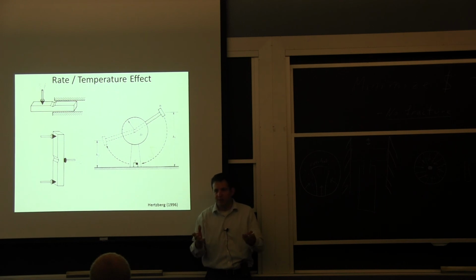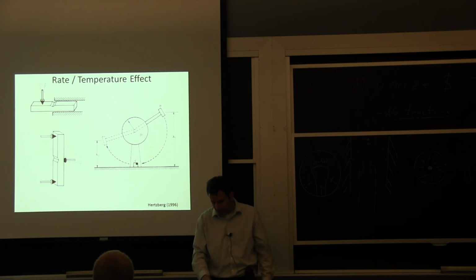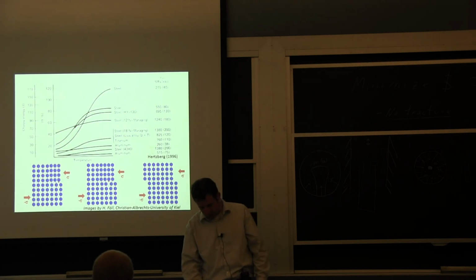But it's giving you a combined response. It's only as good as what you're testing. So you're testing the material under a condition where you have a notch. It's not a crack, it's a notch. And then you're loading it rapidly in all those cases. So that's what we call the impact test.